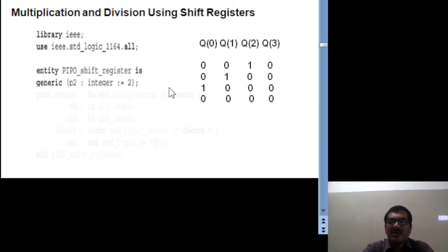After that, the input output ports are declared. That is port of number. Okay, number is one signal object. It is input to the system, and it is declared in the form of a vector consisting of 8 bits, 7 down to 0. Port of number colon in standard logic vector of 7 down to 0. So 8 bits it consists. The number is a signal that has to hold 8-bit data. That too, this is the input to the system.